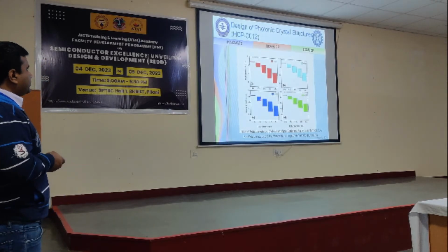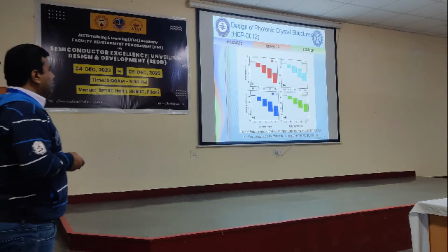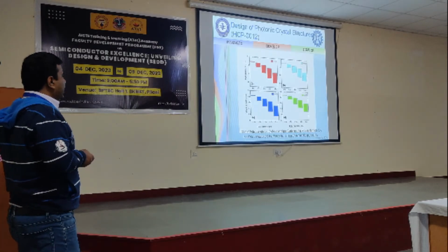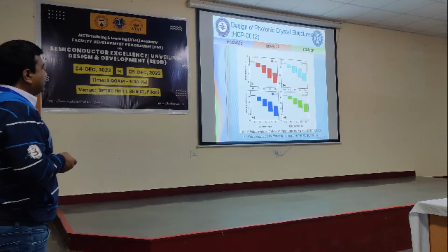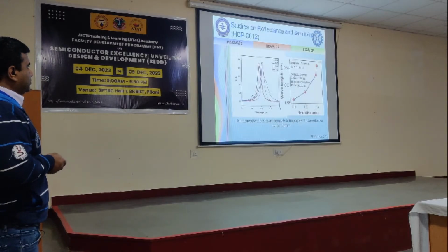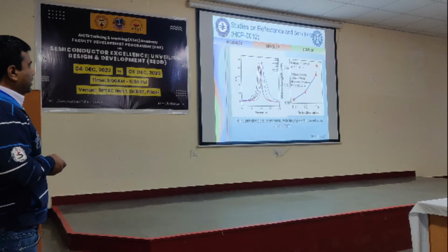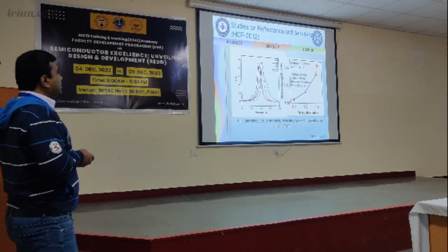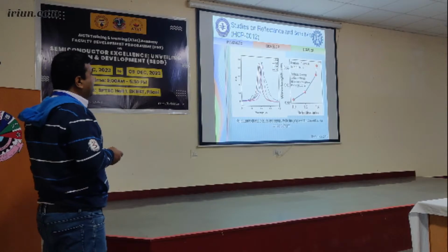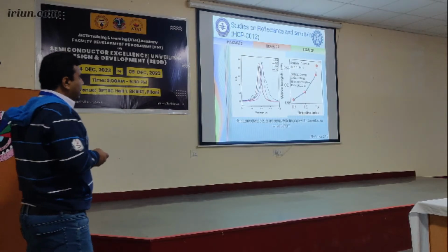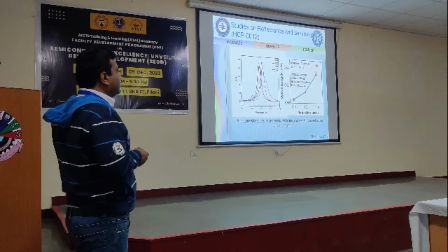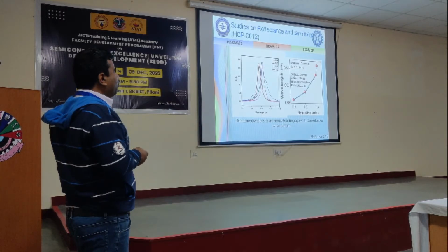You see, in that case also, with variation of hole diameter, you can find the wavelength in these cases within the photonic band gap region. Now you see this is the reflecting characteristic of the devices, and the sensitivity of the device was found to be 91 nanometer per refractive index unit, when you are varying the refractive index from 1.1 to 1.4.